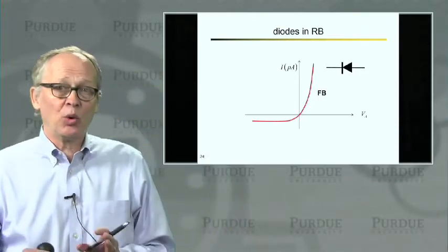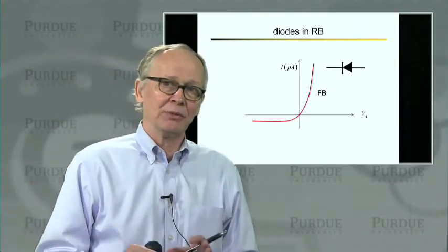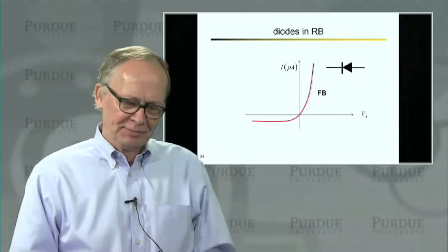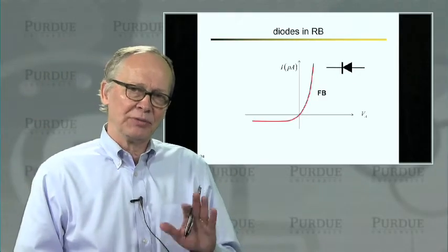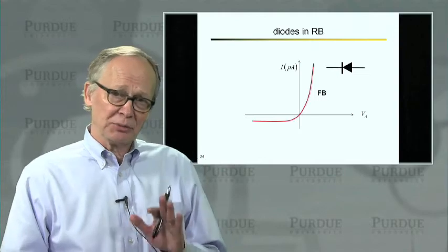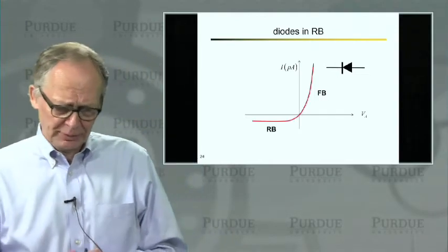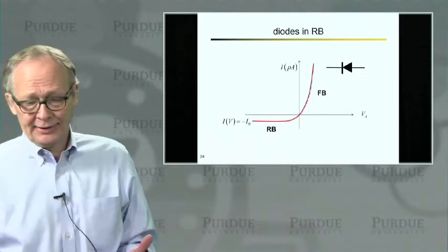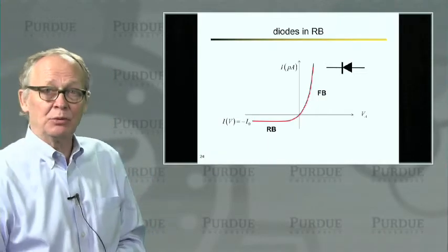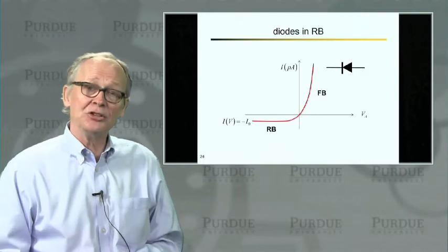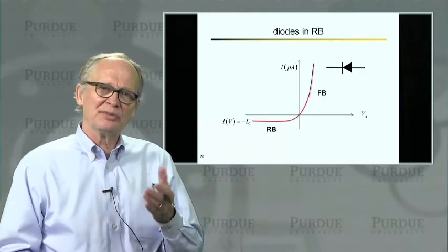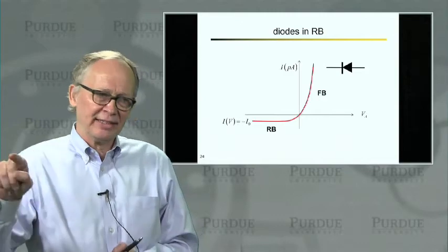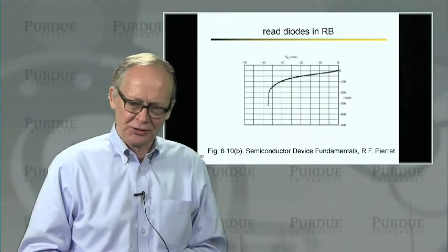We've talked about one big non-ideality in reverse bias, that's breakdown. But let's not go that far. Let's look more carefully at reverse bias in the modest reverse bias region before it breaks down. Our ideal diode equation says the current is constant. It's just equal to minus the saturation current, independent of voltage, once the voltage is more than a few kT, so that e to the minus few kT over kT is about 0.